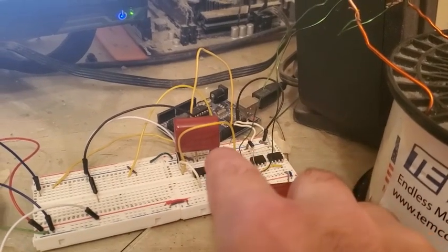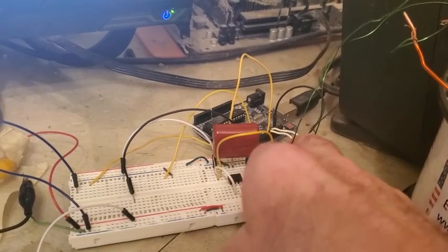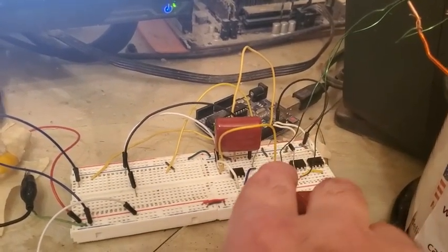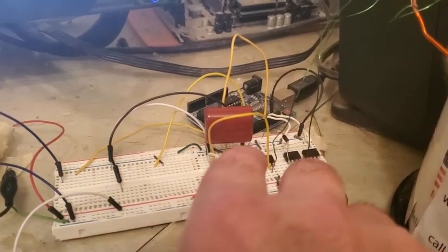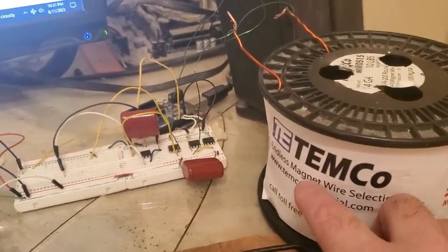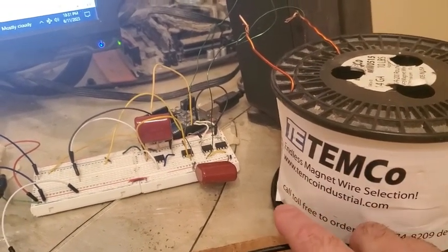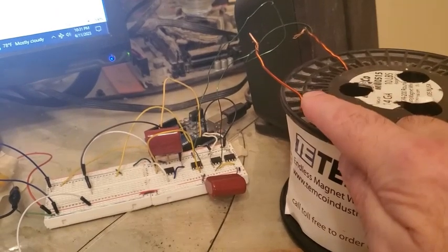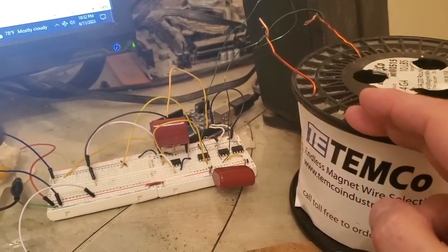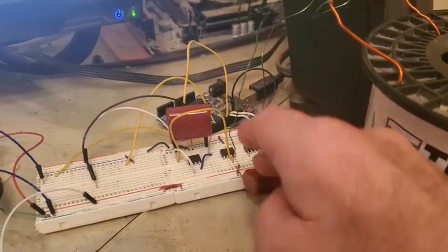Oh, and the other thing is to look at synchronous rectification, and we don't need this stinking diode. Get rid of the diode. The thing that I'm curious about there, and I don't know whether I'll have success or not, is that as I mentioned before, you've got 2 fluxes here. You've got when this thing is charging up, going from 0 to charging up, and that would be non-inverting. And then you have when it collapses, and that's the inverting that shows up as the -8 there.